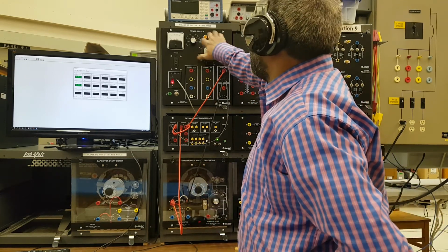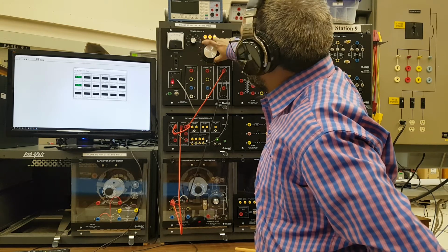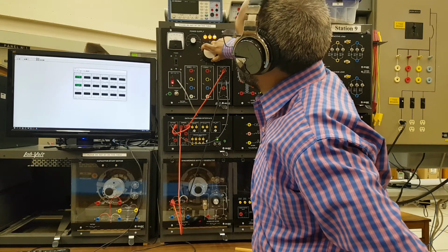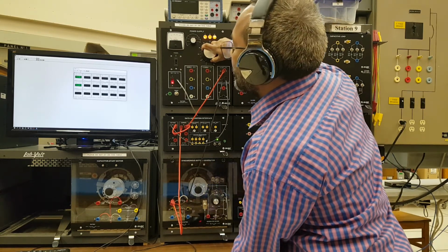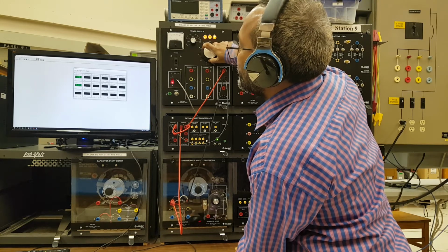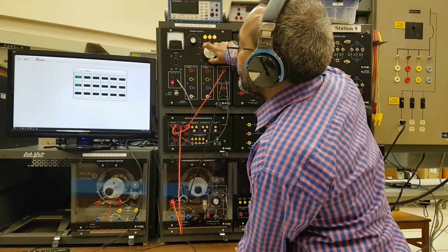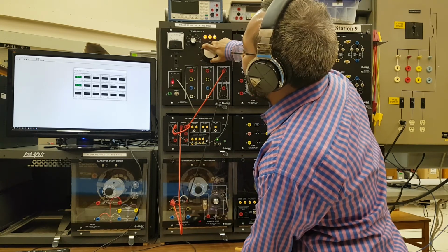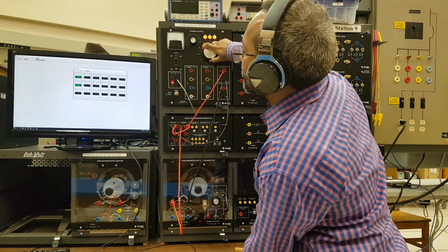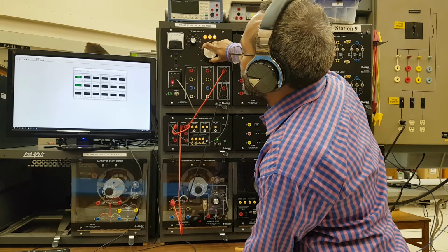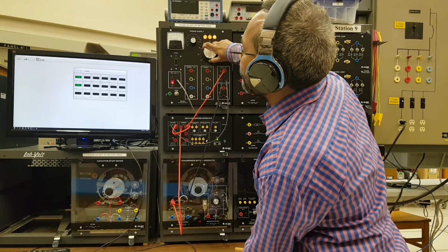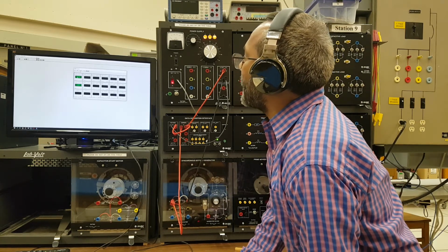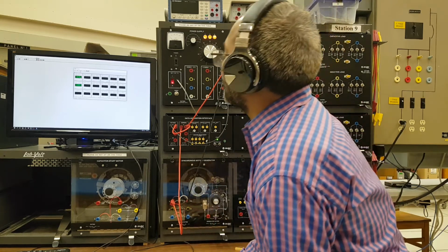So turn on. You can see that the current is changing fast as I increase it. So you have to be very careful. While watching, this should be 1 ampere here. So 1 amp, 0.75, 0.81. I'm at near 10 percent of the dial, but still about 86 percent, that's why you have to be very careful. You don't go to 100 and kill the winding. So this is 1 ampere here, and it's applying 12.64 volts. So I will take the reading.